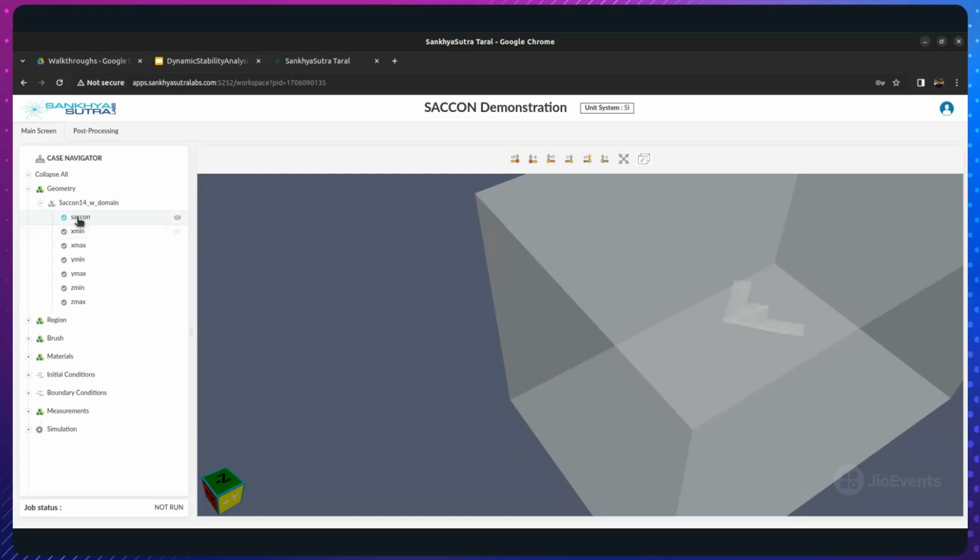As soon as I applied the resolution, you see that my gray box turned to blue. So for any patch that you apply a specific patch resolution, it will turn blue here. And any patches that do not have any resolution attached to them will be shown as gray. So you can do this for one or more patches here.